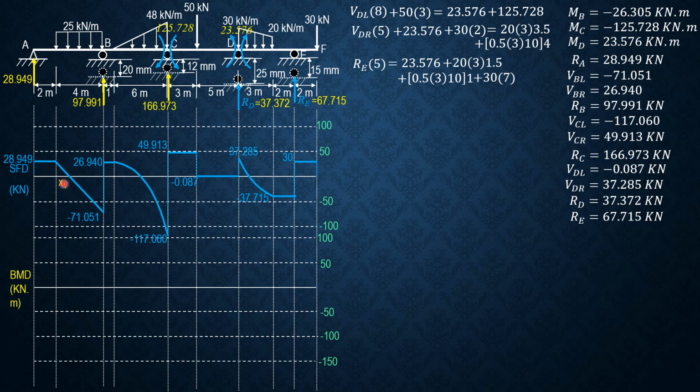So we will call this distance x1 before we solve x2 from this point to that point where shear is 0. Then this one as x3. Call that area 1, this one area 2, then x3 here, then area 3, and this one is area 4. Those are the areas that we shall compute. All the rest can be computed easily because they are just rectangles and triangles.